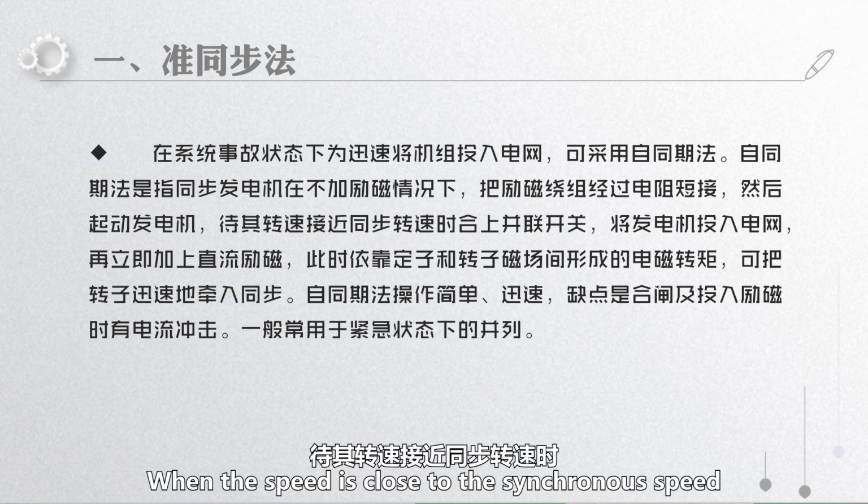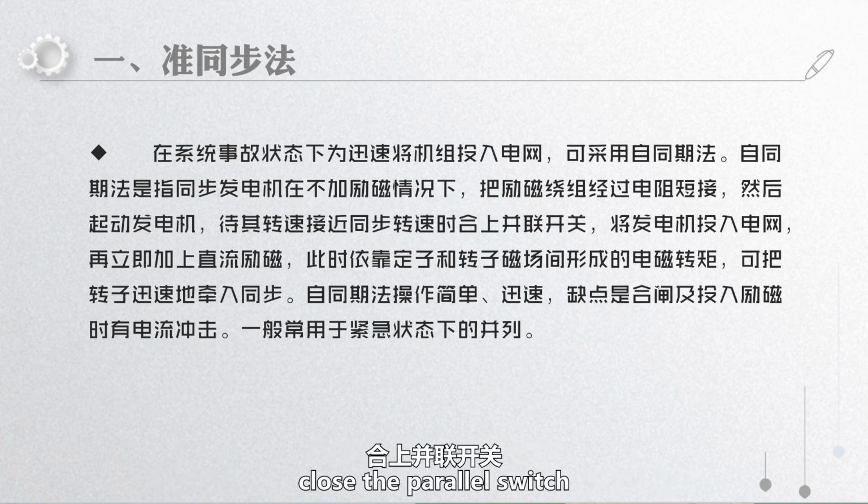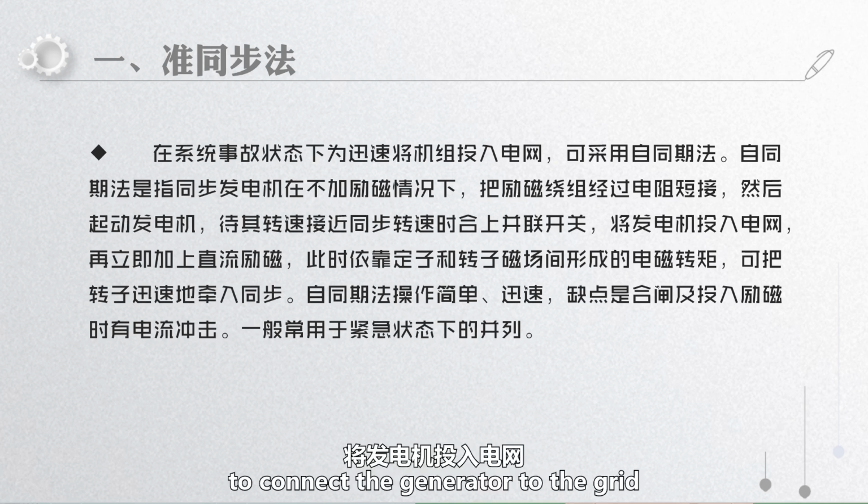When the speed is close to the synchronous speed, close the parallel switch to connect the generator to the grid.